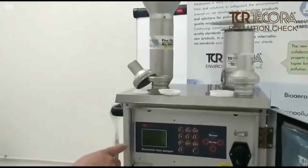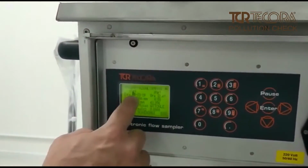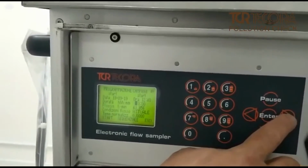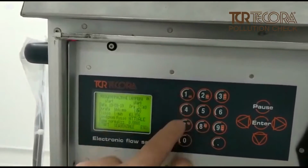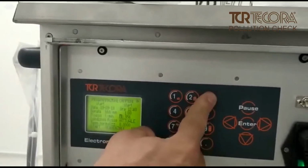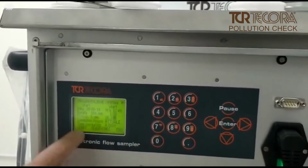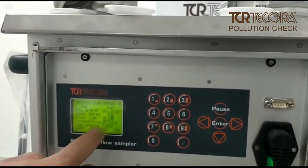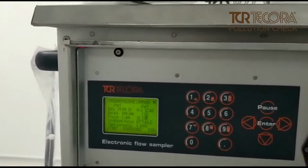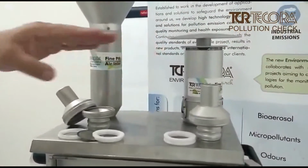Now, if you would like to enter deeply into the programming, we can, for example, leave the date and time, that is the actual condition that we have here in Italy now. We can plan, for example, 1 hour sampling, so hours and minutes, 1 hour. Then we can set, for example, the European flow, that is 2.3 cubic meters per hour, in order to maintain the right cut-size point for PM10 or PM2.5 according to the European norm.